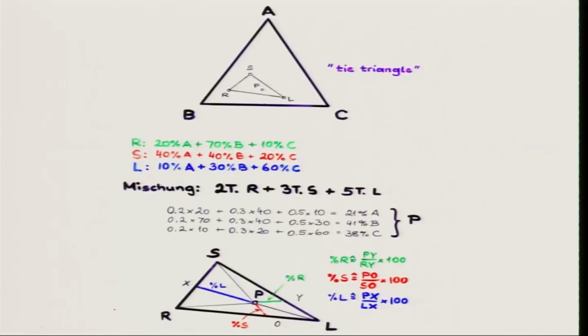Students, so we have started discussing three-phase equilibria in ternary systems, and I just told you that the three-phase equilibria consisting of alpha, beta and liquid can be represented by a ternary triangle. I hope you remember that I discussed ternary triangles, and this is basically a triangle connecting three phases, and I have given you a brief outline of that. So, before that, let me just tell you how a ternary triangle looks.